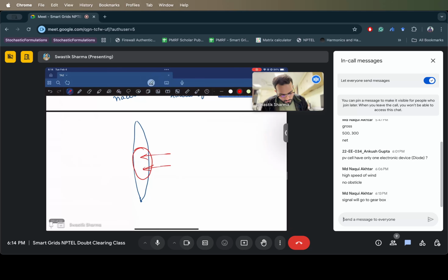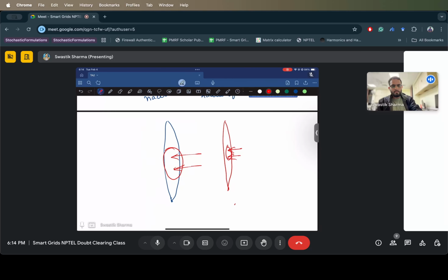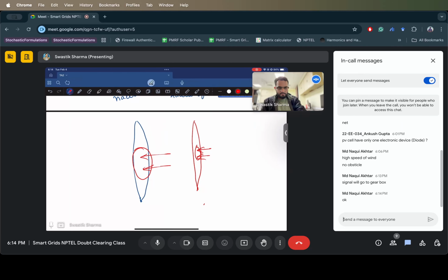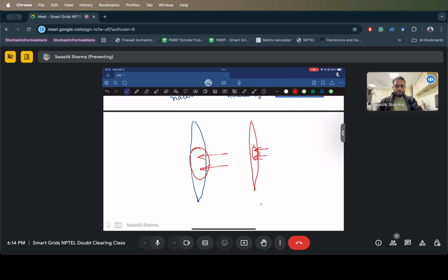So how do you control the pitch? You rotate the blades like this. You change the blades a bit. If you can see my camera, let's say earlier your blades were like this. Now you shift it like this, so that the attack is minimized. Now not all of the wind falling on it can rotate it, right? So the attack is less. Now the speed will not be that much, right? So that is the usage of this, right?